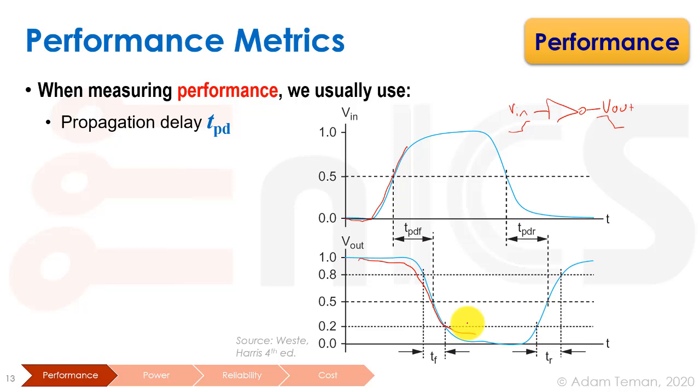The propagation delay is defined as how long it takes for the input to rise until the output falls for an inverting logic path. And usually we have to define some singular point where that happens. So for example, in this definition, the threshold of 50% of the supply voltage is crossed at the input until 50% is crossed at the output. It can use different definitions, such as 40% of the input to 60% of the output, or 60% to 40%. The most important thing is that our libraries are made to use the same metric.